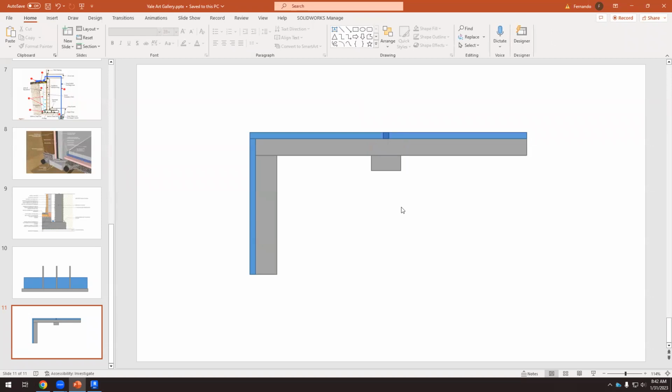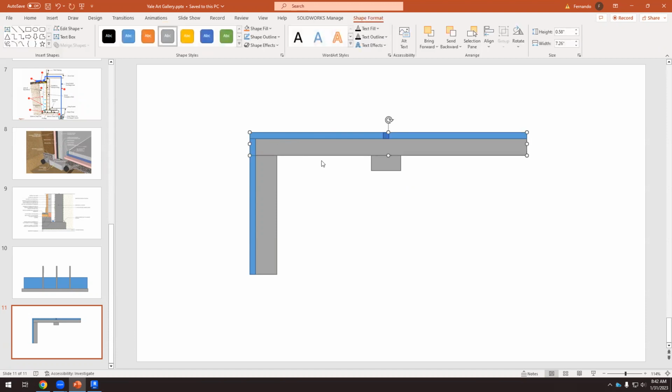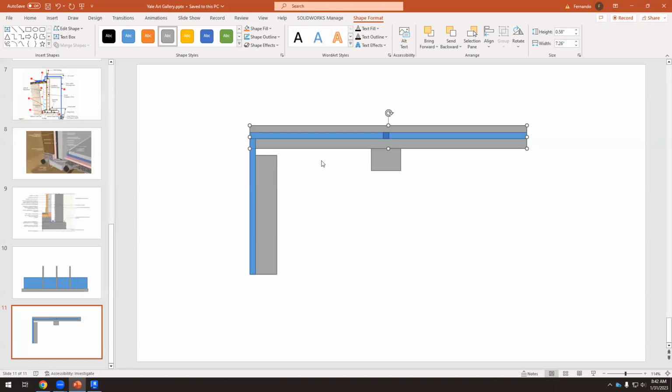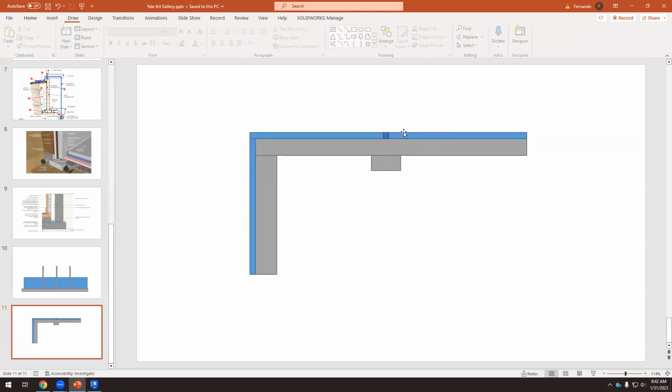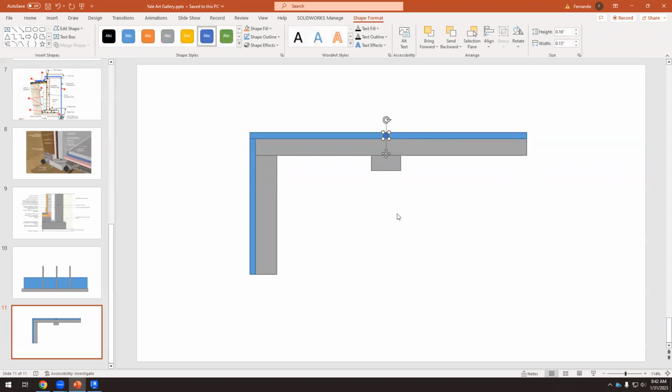Okay, so that might happen. First, I have a wall. The wall, I can't put this centered column footing, so it should be like this. But if this part of the site is not mine, then I need to line up the footing with the wall here. And then we need a reinforcement.